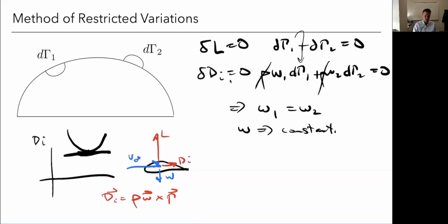So let's imagine I've got this wing here, and now I rotate it 90 degrees. So before the straight wing, my circulation was going left to right. So now if I rotate that, gamma is now pointing up here on this view. So gamma is up out of the page. So V cross gamma gives me a force perpendicular to that like this, right? So if this is a right angle like this, that's the force that's introduced.